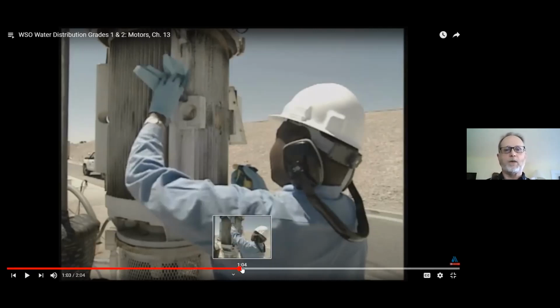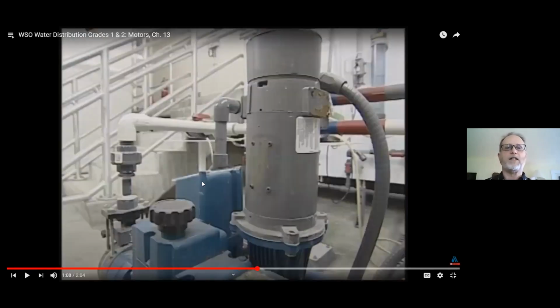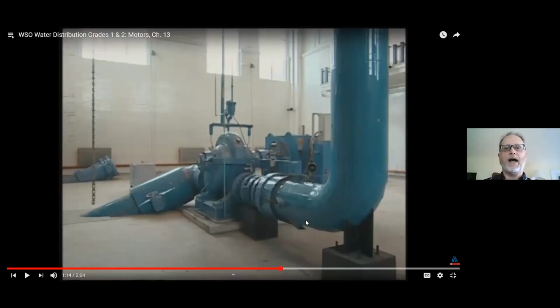The other key thing that will show up on the exam is the difference between a single phase requiring direct power to actually create the rotation, versus in three-phase where you have the ability through the motor to actually create torque. But because there is such a huge draw of power when that first switch is turned on, pump manufacturers will pair them with motors that have various capabilities.